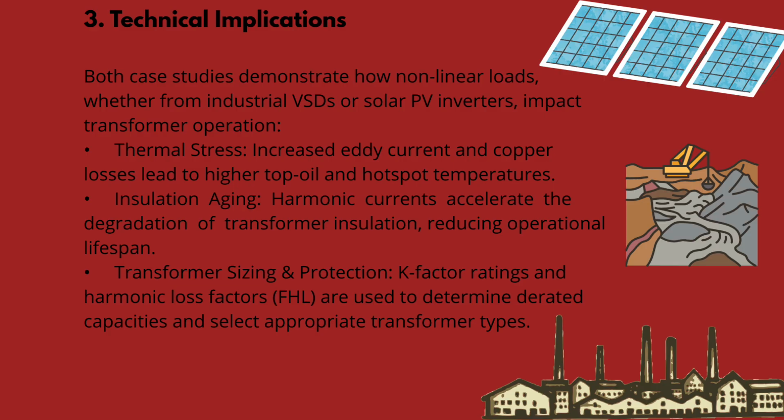Technical implications. Both case studies show that nonlinear loads such as industrial VSDs and solar PV inverters significantly affect transformer performance. Harmonic currents increase thermal stress by raising copper and eddy current losses, leading to higher oil and hot spot temperature. This also accelerates insulation aging, reducing transformer lifespan. Therefore, proper transformer sizing using K factor ratings and harmonic loss factor is essential to ensure safe operation.